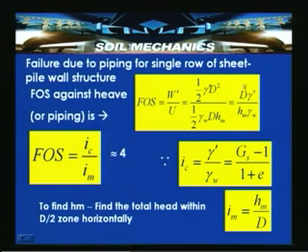So, with that, Hm by d is referred to as the mean hydraulic gradient Im, equal to Hm by d. Here, with a head Hm, d is the length of the flow. That is the gradient over which the flow is taking place at the downstream side of the sheet pile wall. Now, if this factor of safety Ic by Im happens to be approximately 4 to 5, then we can say there is an adequate factor of safety against piping or heaving failure. If this value comes out to be some 2 or so, then we can think that the structure is unsafe against piping or heaving failure.